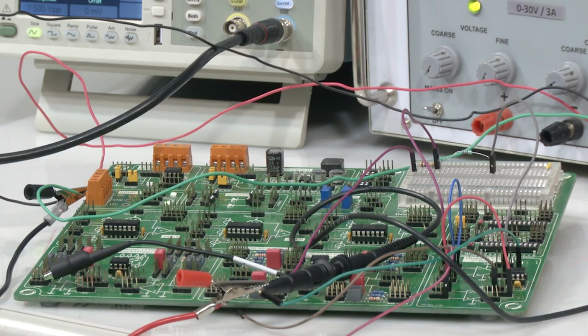You might have seen the experiment 1 description, where we are changing the input frequency and seeing how the input and output voltages are changing, correct. So this is related to what is called gain bandwidth product. The gain and bandwidth product of a feedback amplifier circuit remains constant. So if you have a higher gain, the bandwidth you get will come down. Accordingly, if you have a lower gain, the bandwidth you can get is higher.